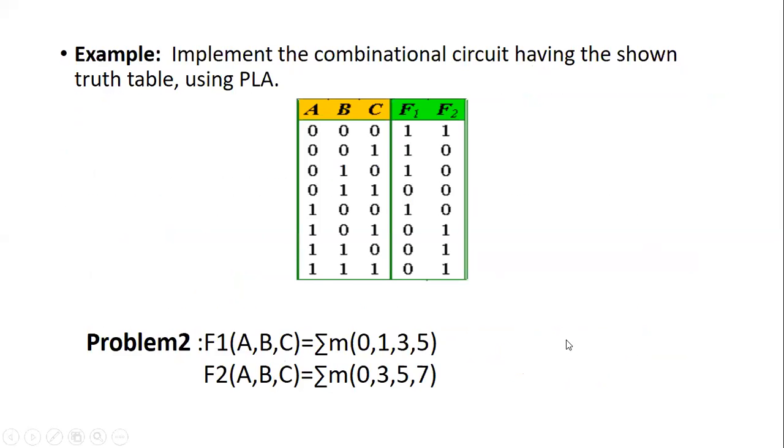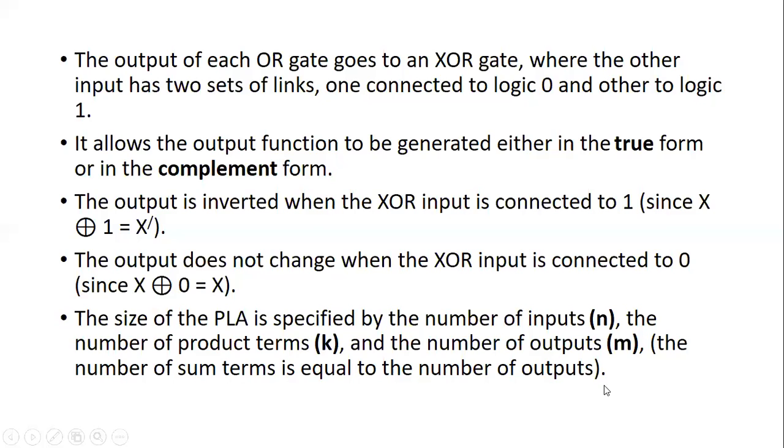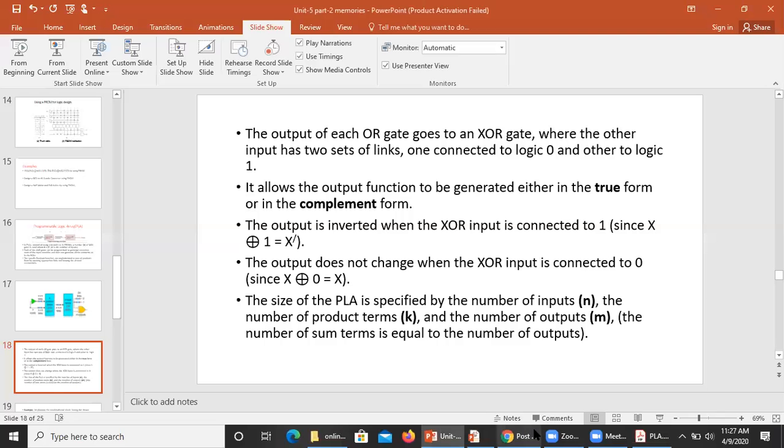After considering this, you need to draw a PLA table. This PLA program table contains the product terms, the inputs in each product term, and the output, whether it is in the complemented form or the uncomplemented form. Now let's consider the previous example.